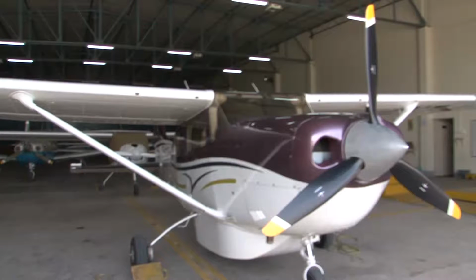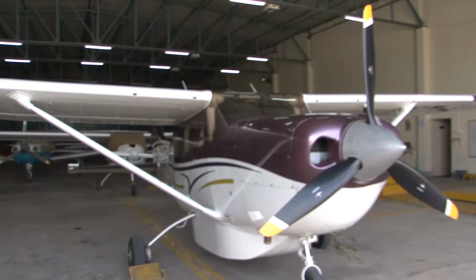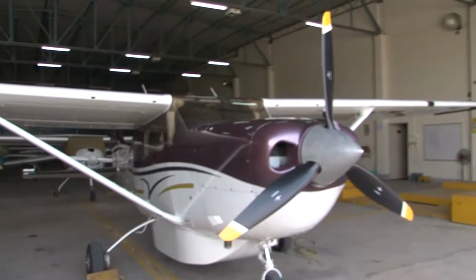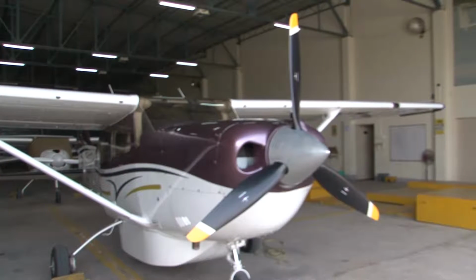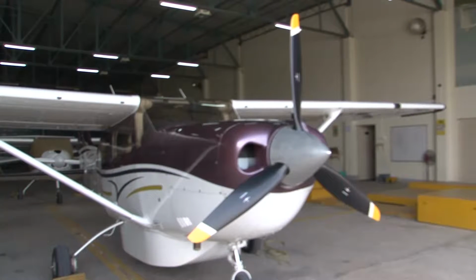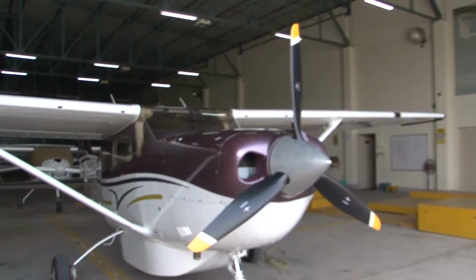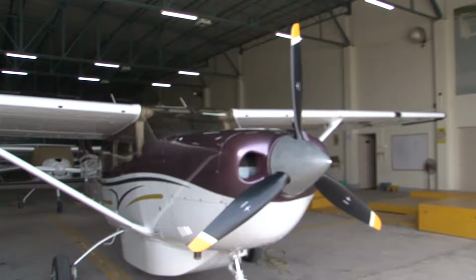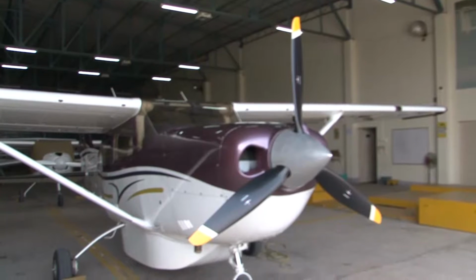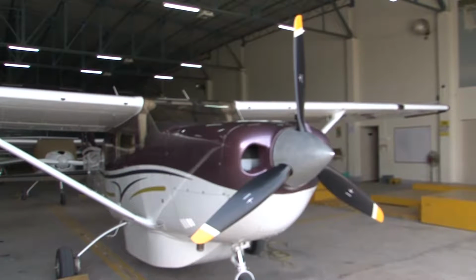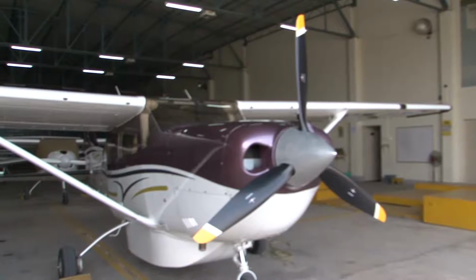That is, you can keep the length around 75% of the span to start the initial conceptual design, right? And you'll find mostly that will conform to a conventional airplane. That is, the total length is around 75% of the total span. This is an important observation you must keep at the back of your mind. And also, another question will come to your mind: what is the maximum diameter of the fuselage?